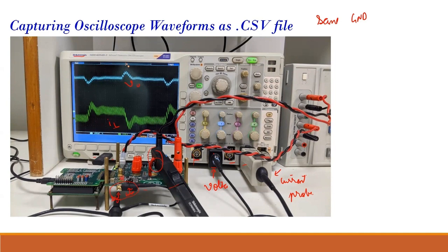Then the second probe, I should not connect to the second ground, right, sir? Yes. Otherwise I'm shorting both the grounds. Yeah. So in that case, you need a differential probe. In that case, you need a differential probe. And differential probes are very costly.